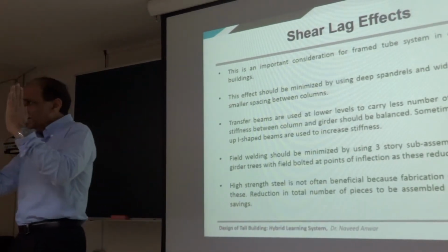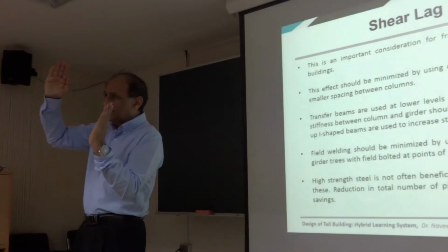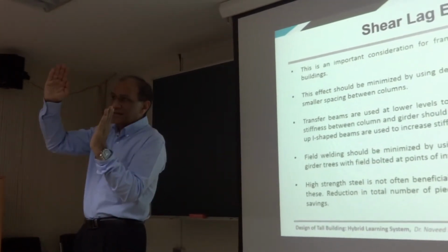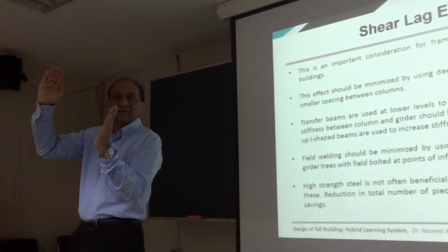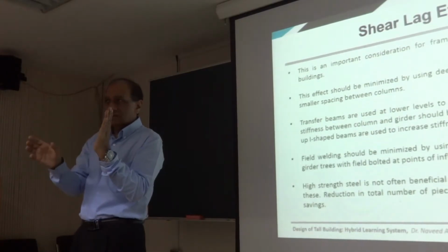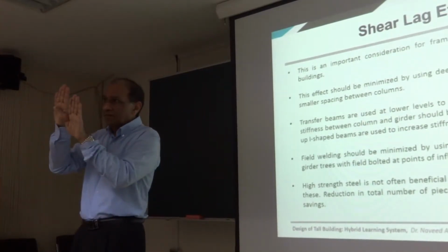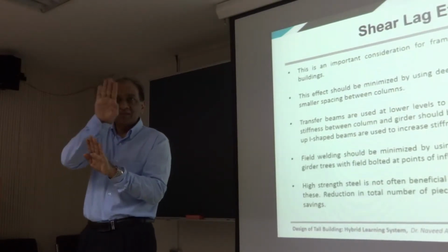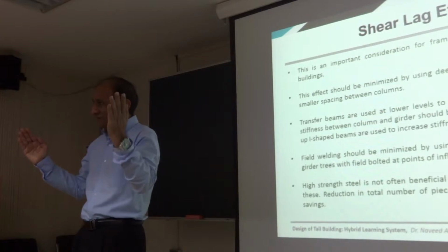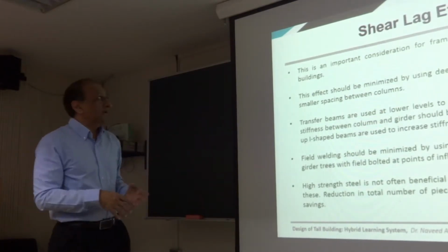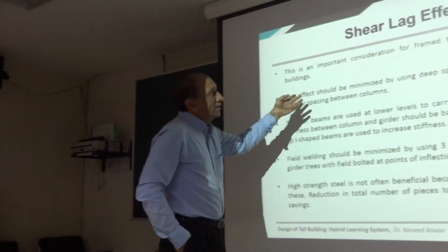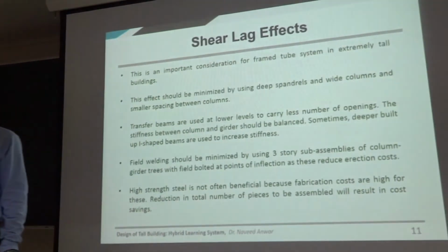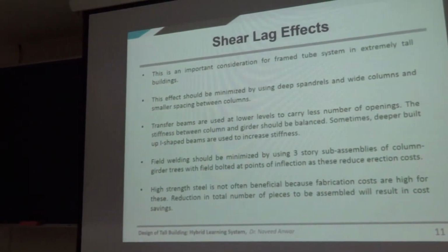So from this side to this side, you do not get a straight bending as you would in a solid cantilever building, because of the shear deformation of the beams and slabs and other things that connect this face to that face. So that shear lag effect is quite important in most of the structural systems that we will be discussing.